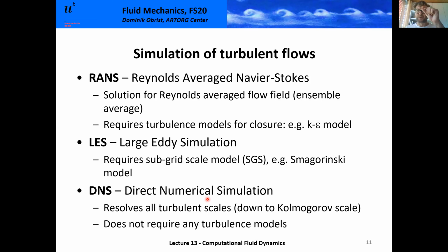Now we have seen how small these small structures can become, and that shows us immediately that the grids can be prohibitively large if you want to do a DNS of a flow at very high Reynolds number. A DNS of a full commercial airliner is completely impossible. Anyone who tells you otherwise is wrong. It's not possible and will not be possible for decades to run a full DNS, meaning you resolve every single little sub-millimeter vortex on a whole commercial airliner.